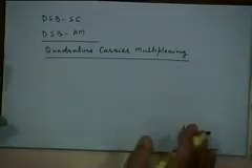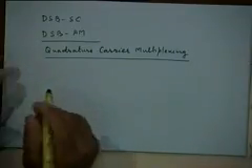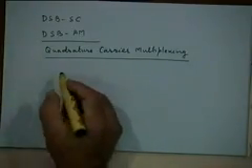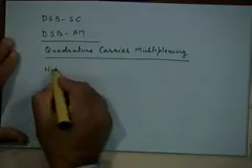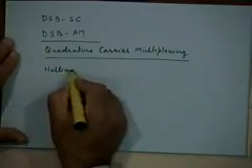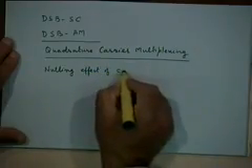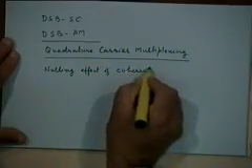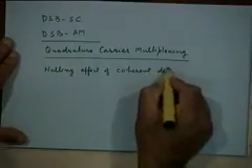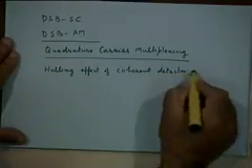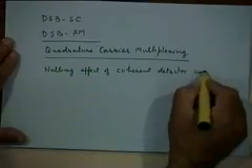Normally we don't think of putting two signals in the same carrier. So we are here using the nulling effect of the coherent or synchronous detector to advantage.